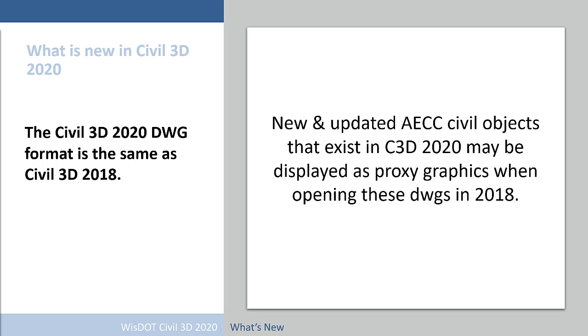One caveat to this is that some new and updated civil objects that exist in Civil 3D 2020 will be displayed as proxy objects when opened in 2018. So though you'll be able to see the objects and query them, civil objects that have new version functionalities in them will be presented as proxy objects. As of now, most civil objects like surfaces, alignments, and corridors are all backward edit compatible.